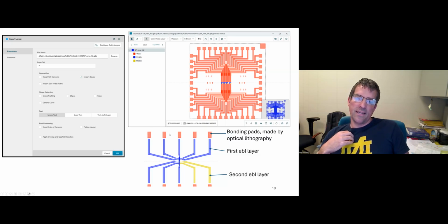From here, there are these red rectangles, which is just a zooming part of the center part of this bonding pad. This is something that was done by optical lithography, and my nanoscale devices are going to be exposed by E-beam. But I actually imported into Layout BEAMER all the optical lithography part, because then it will make setting up your CJOB file much easier. And then in the E-beam, the 2 different colors are the 2 different layers that I'm exposing.